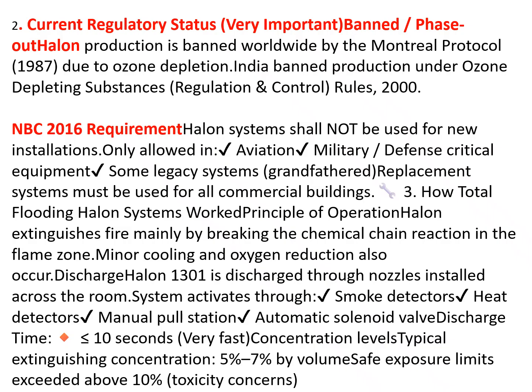Now, how a total flooding halon system works, the principle of operation. Halon extinguishes fire mainly by breaking the chemical chain reaction in the flame zone. Minor cooling and oxygen reduction also happens. Discharging halon 1301 is discharged through nozzles installed across the room.